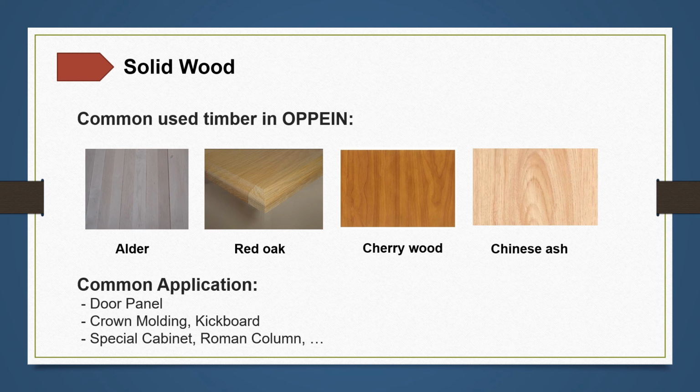Normally for hinge doors, the grain direction is vertical grain. Same for the fake doors and fillers. And for drawer panels, door material kickboard, top panels, and light cornice, their grain directions will be horizontal grain. If there's a special need for grain unity, you can adjust the grain of drawer panels and make vertical grains as well.